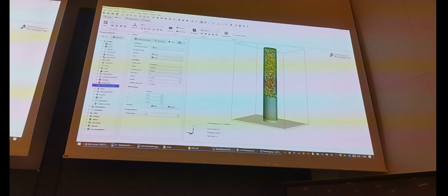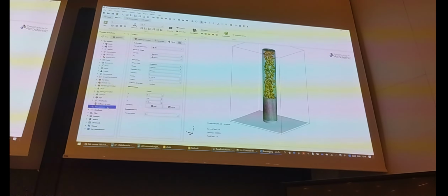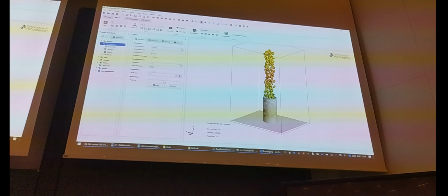So I have my donuts here, and when I go to simulation now, they should... What should they do? Let's see if anything happens. Nothing happens. Why? A very, very important thing that we have here on Earth, different to the moon: gravity. We didn't define any gravity yet.